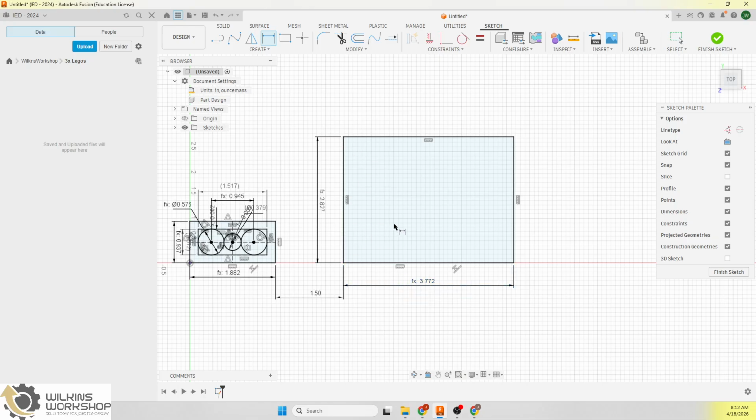We could also think of it this way. If you did a 1 by 2, a 1 by 2, and a 1 by 2 sitting right here, you should have 3 of them with an air gap here and an air gap here. So you'd have 0.008 there and 8 thousandths here. So you should have 16 thousandths difference between this number and 3 times this number. So if we tried that, 2.827 minus 3 times 0.937, I get 0.016.